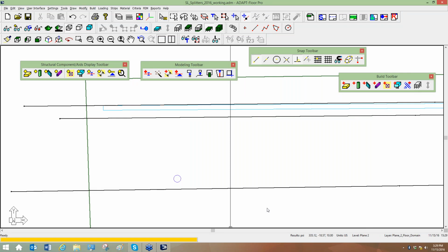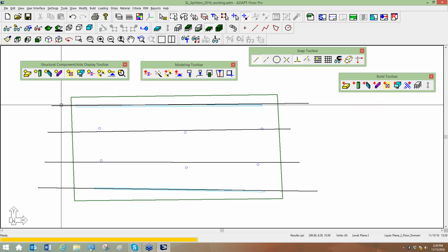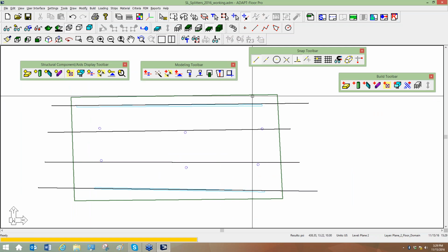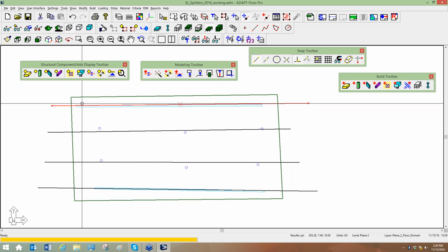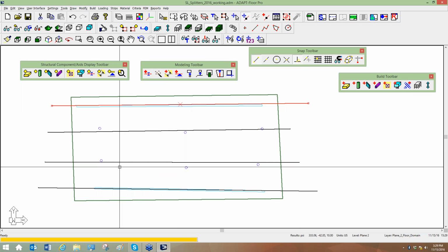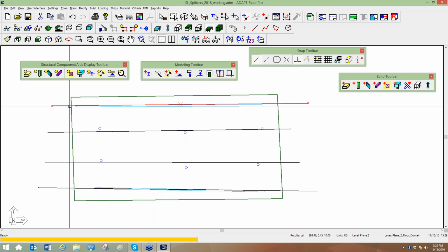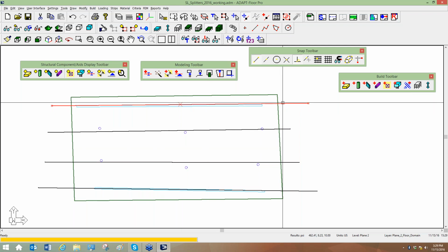Okay, and the next question was, where a slab is supported by walls, does the support line need to be one way? Let me go back. So here's a continuous support line. This slab, in this direction, I would still consider two-way, because the bending is really two-way bending out in the field. Ultimately, you're just not going to get any bending over the support line if we refine the input of support lines like was just shown.